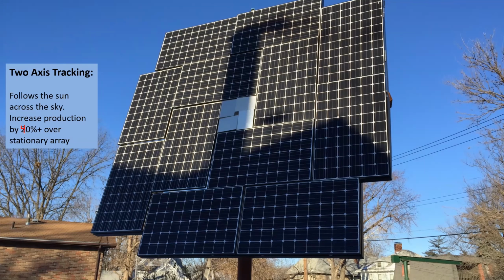I say a ton. I've got a more complex moving part, because now it's just going to face the sun wherever it is. In the summer, it's going to face more straight up. In the winter, it's going to face more to the south. And what it has a lot of times is a little device that looks at the sun and can adjust the angle of it. These break down much more often because they're more complex moving parts, but they do get quite a bit more production. They do cost a lot more.